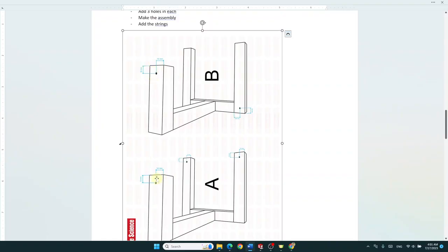The hole on the smaller part that's going in the middle is at 14 and 8 millimeters, both of them. So let's do this hole first, and after that I will save the two parts with two different names and make the two holes. So we have dimensions for the hole. I will make a little hole of, let's say, a diameter of 2 millimeters. And we have 8 millimeters and 14 millimeters.